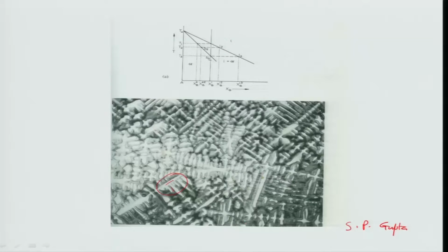Ferric chloride will react with copper and remove the regions where copper is present, and those regions will form microdents, and therefore in optical microscopy they will look dark. So here you can see the dendritic cores are rich in nickel, that is what we have seen in the earlier picture. On the other hand, dendritic peripheries are rich in copper or otherwise lean in nickel.